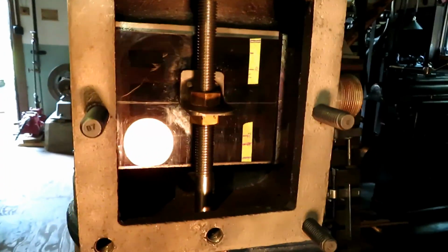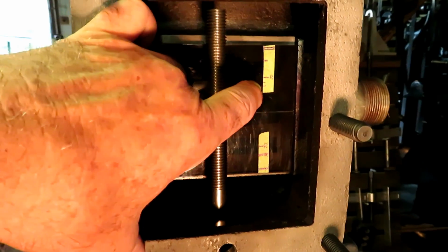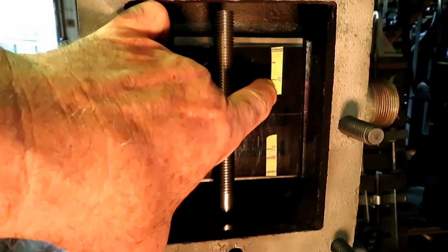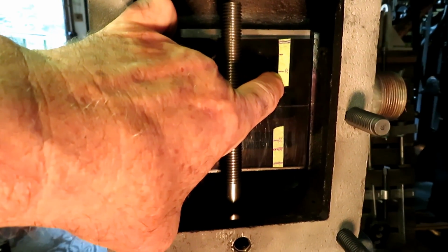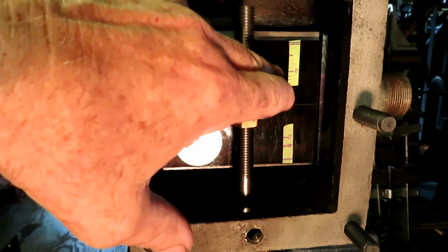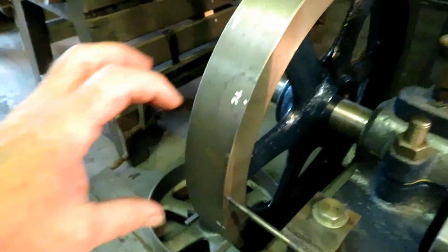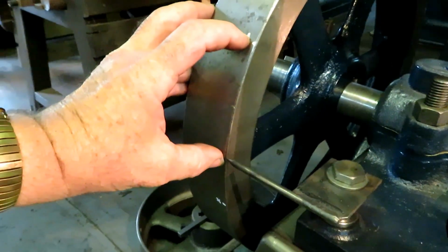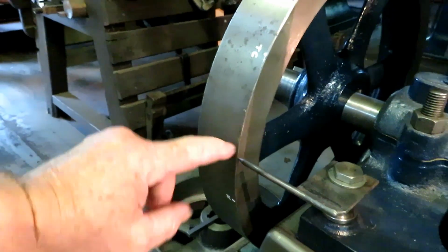And I've turned the cylinder back to the end of the exhaust stroke where the release mark is closing up on what would be the cavity on the back side of this, and you can see it's that far before top dead center. That's the cushion where the steam is being compressed.